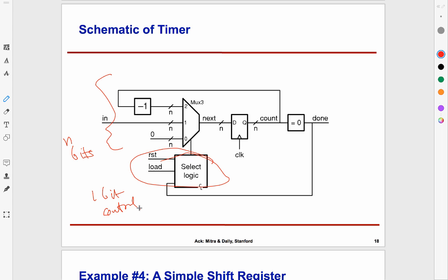That n-bit data is kind of like a variable. If we are manipulating the count, we are saying make the variable 0, make the variable +1, stuff like that, the typical things we do in a program. And the stuff out here, this control logic, which I've called the select logic, is where the control flow is happening. It's controlling the multiplexer or multiplexers, if there are more than one, to make things work out.